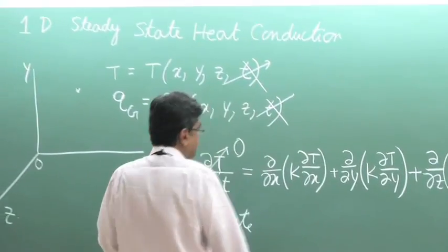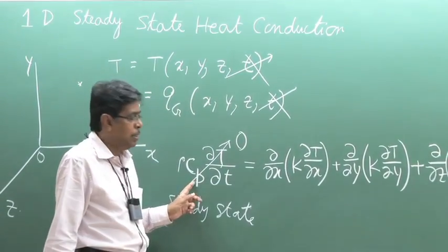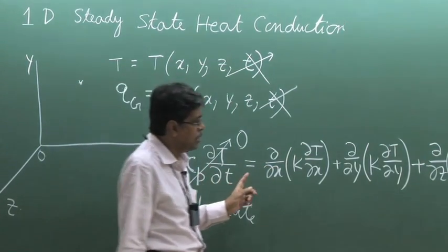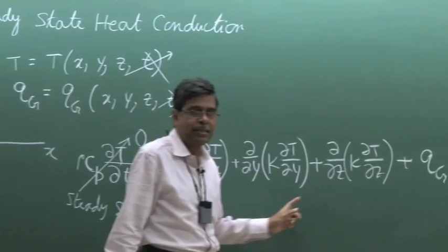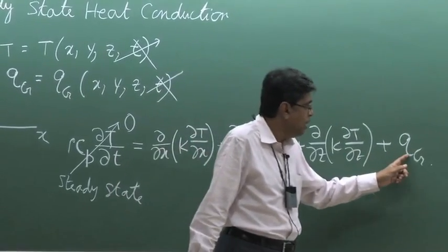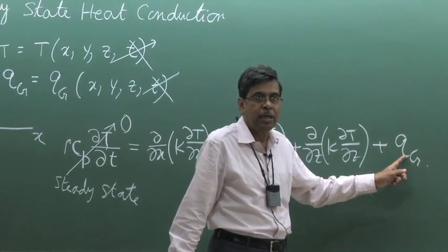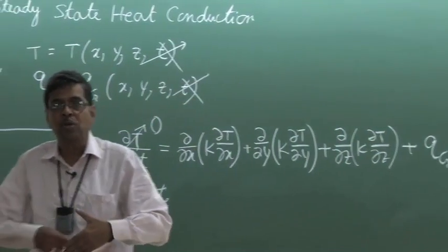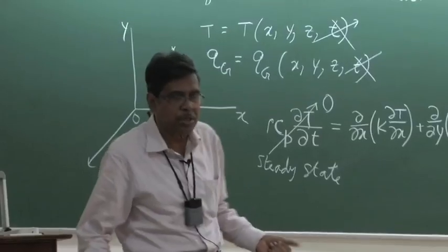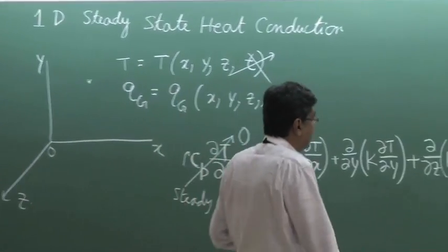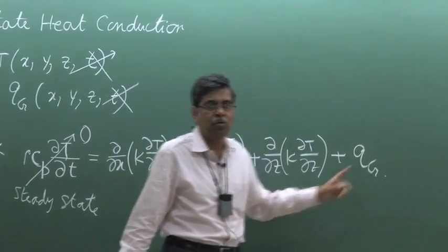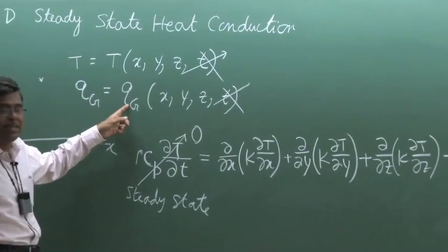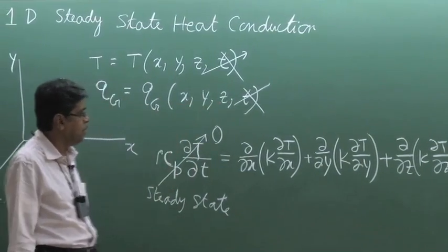Now mathematically this becomes 0. Then therefore, this right hand side equals to 0 is the general heat conduction equation in Cartesian coordinate system with heat generation, Q thermal energy generation. Sometimes I may say heat generation, which is usually told widely, but this is not strictly correct; it is generation of thermal energy, and this nomenclature is generation per unit volume, which is a point function, and in that case under steady state this will be a function of x, y, z.